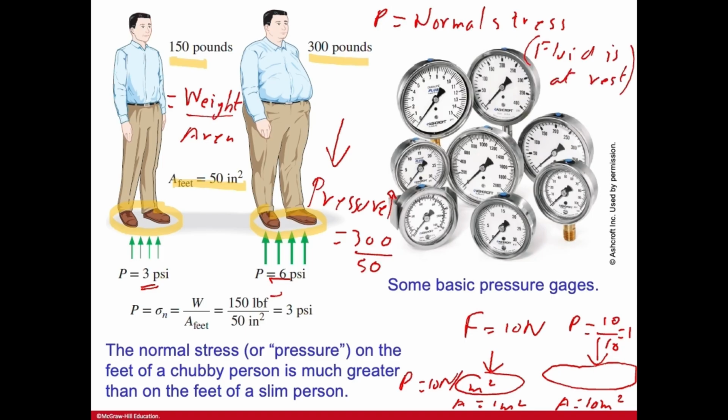So essentially the fluid is not moving. Always keep that in mind. If it's a moving fluid, pressure might not directly be equal to normal stress. Remember that this pressure equaling normal stress is only for fluid statics, if there is no dynamics involved for the fluid itself.